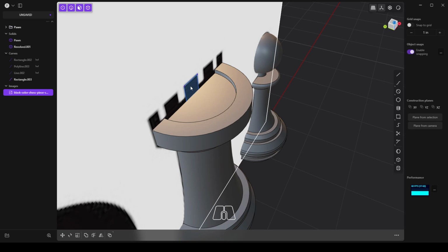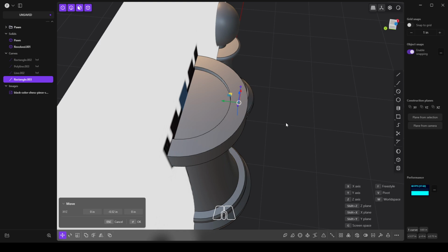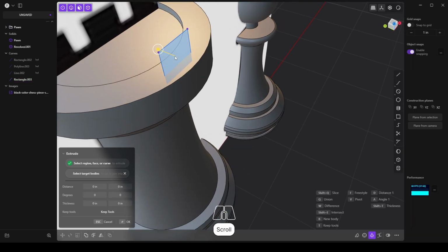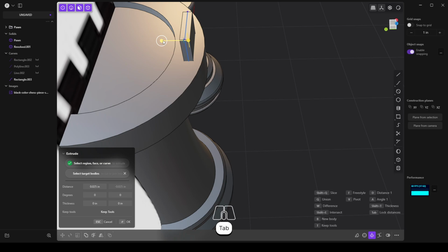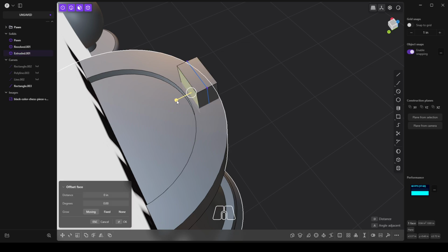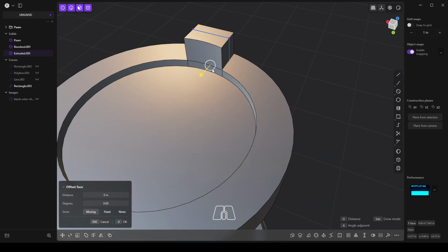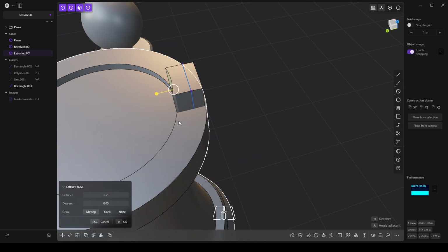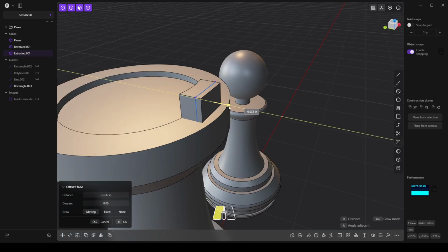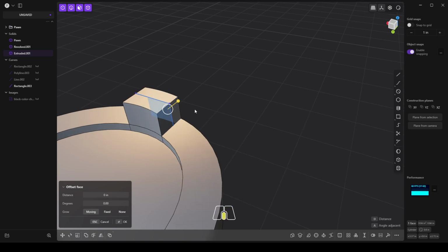Let's grab that piece here. So I'm going to grab that. Let's use G. I'm going to move it into a position like so. And from here, let's just grab this. Let's use the E key, okay, to go into extrusion. I'm going to use Tab, and then hopefully I can get these roughly to this area here. So let's just grab that. Hide the canvas there so we can see. So there we go, we've got a nice curvature there, and we'll do the same for this one as well. So let's just grab that, and it maps over the face there quite nicely, so pretty good.